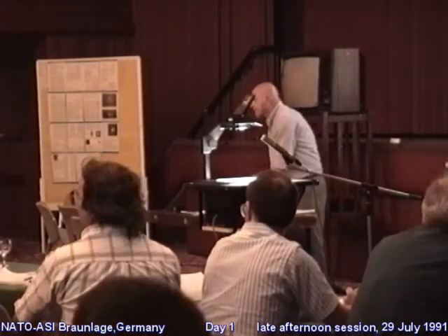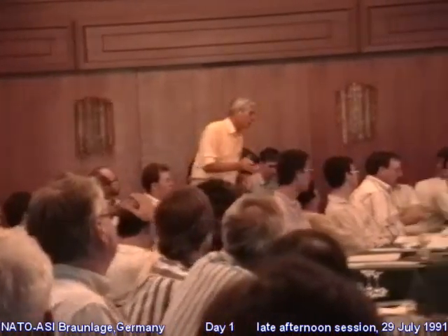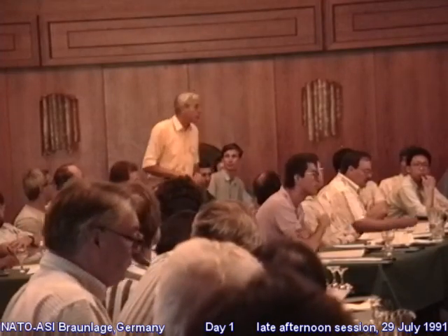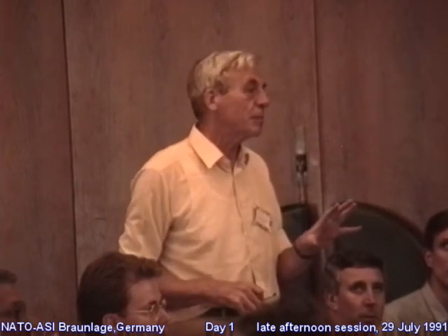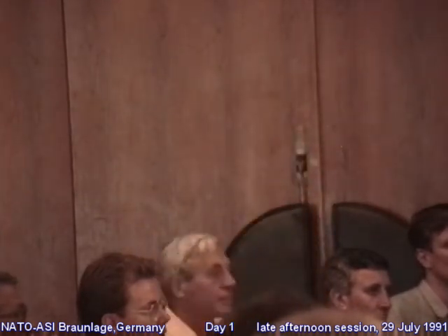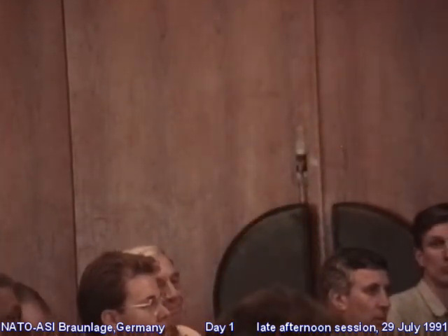This is really on what you said, that an important effect in an interaction meeting like this was to bring together this sort of work with continuum mechanics. You impressively showed contours of hydrostatic stress and the local areas of hydrostatic tension at the edges of the contact. That's consistent with continuum ideas. But in order to make these comparisons more effective, we need to know the deviatoric stresses as well, the shear stresses. Is there any difficulty in principle in providing that information? No, we actually published some of it, so I will show you exactly.